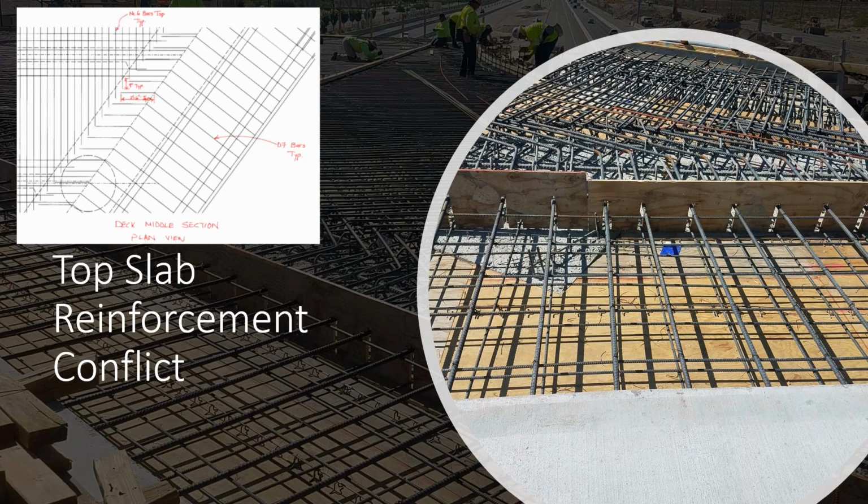Another thing here is the detailing of the top slab reinforcing. I had to bend this reinforcing in order not to be in conflict with the longitudinal reinforcing from the deck. And also it had to be short enough so as not to overlap the reinforcing that is in the transverse direction. So we had to make some field adjustments in order to avoid that problem.